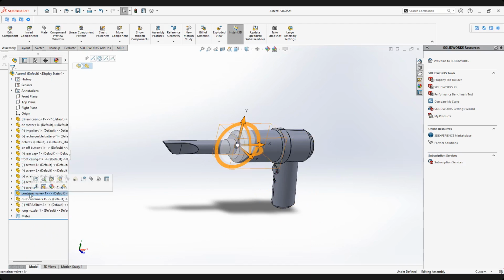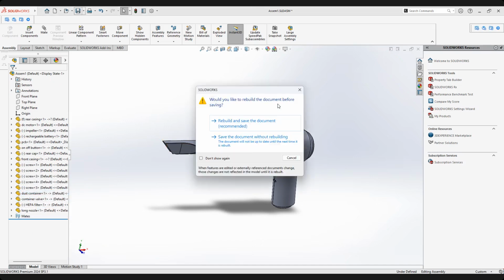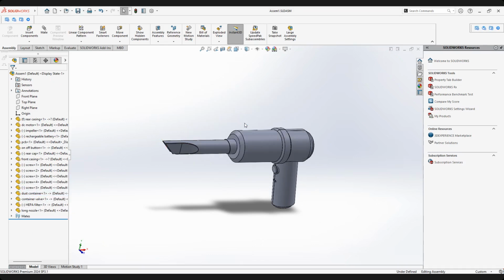Container first or what? Container, dust container, what? Can you see this one, container valve, right? No, it should be dust container first, rack it on top of screw. After screw will be the container. Then we will mount the container valve. Then we mount the filter. Then last one, nozzle. So that's the order. Are you with me or not? All of you.